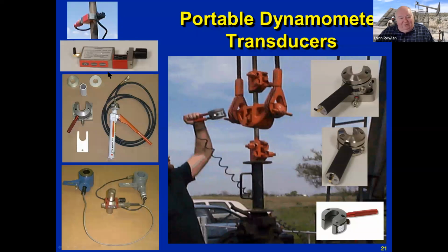So the other way you can do this is you can put a washer on the bottom and a spool around the polished rod right there, and a washer on the top below the polished rod clamp. And the spool is 5 inches tall, and this load cell right here is 4.9 inches tall. You can just walk up and place it right there, quick and easy. And then there's a little spacer plate you slip in between the load cell and jack after you pump it up with this hydraulic pump. You make a 1/4 inch gap there, and you can stack it off very quick and very safe.